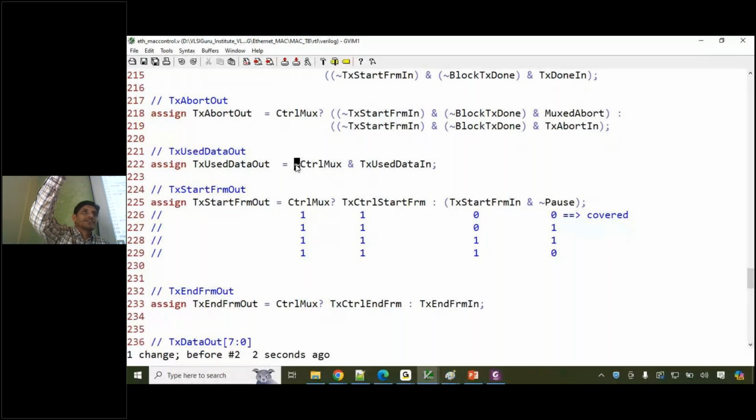Read the specification, list down the features, come up with the scenarios, develop a test plan, develop test bench architecture, develop test bench components. Okay, all that. And through that, he would finally identify this. The verification engineer cannot just go and tell that this file has a mistake. He has to go through that entire process.